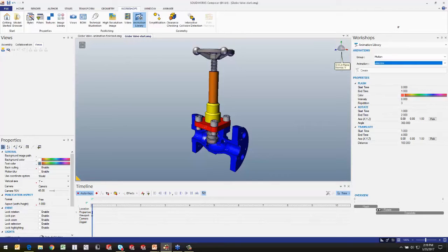We can actually change the timeline here. Just looking at the properties, the start time is 0 and the time is in seconds. So it's going to flash red for a second. It's going to flash 3 times. Then it's going to rotate for a certain distance, and it's going to move a certain distance. If we don't want the part to flash and draw attention to it, we can change the end time to 0, and it won't do anything.